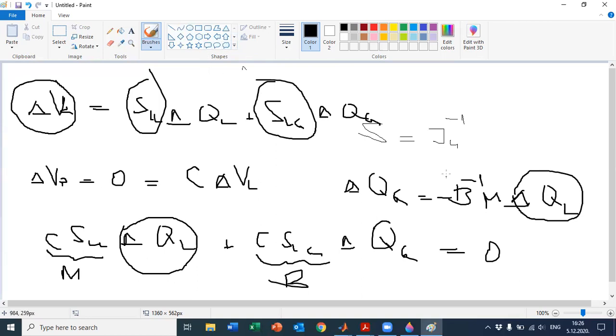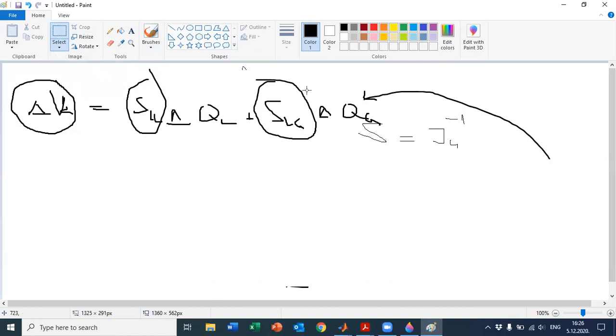So basically, when we determine how to operate the generators to neutralize the voltage deviations, we return this reactive power of the generators into the first equation here, and we get the voltage deviations across the whole network. The objective function, which we are going to be using, and which they used in the paper also, is to minimize these voltage deviations, delta VL. And we minimize delta VL squared, because this makes our problem convex.